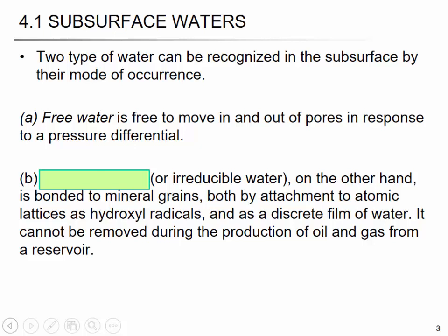And there's interstitial water that's absorbed on the minerals, like the water absorbed on the clay minerals. If you remember the double layer theory, because of the negative charges, it attracts the water molecules and makes the double diffuse layer. Right? So this kind of interstitial water is very difficult to remove.